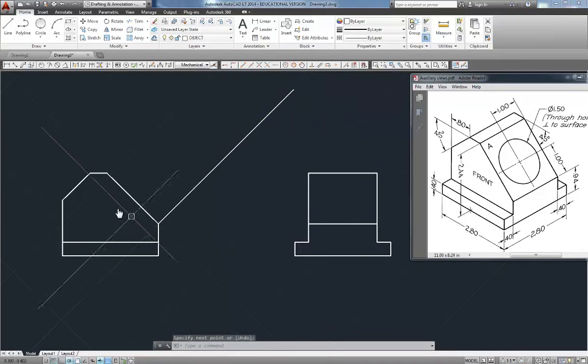Like so. So let's get a couple inches between views here. I'll offset 2 inches. Now, my depths in this view are equal to the depths in this view, but there is no way to project like with a miter line, like we did in orthographic projection. There's no way to project over here. Don't start trying to draw lines between these two views. It does not work, okay?